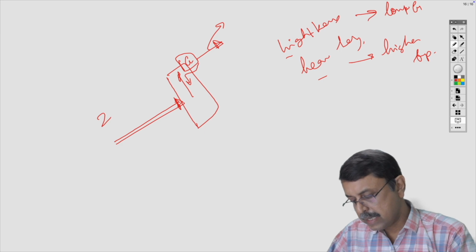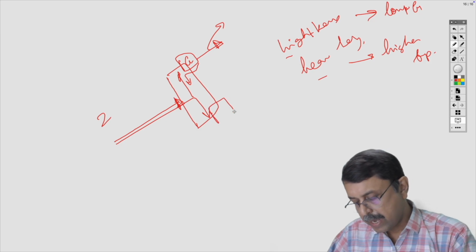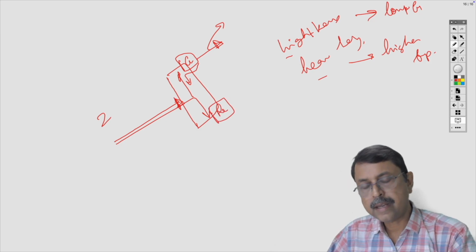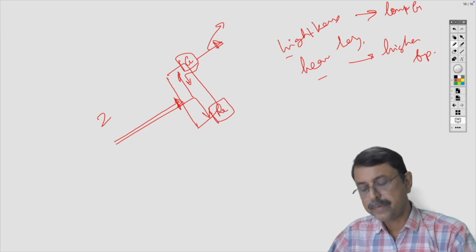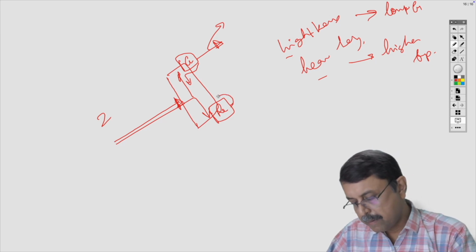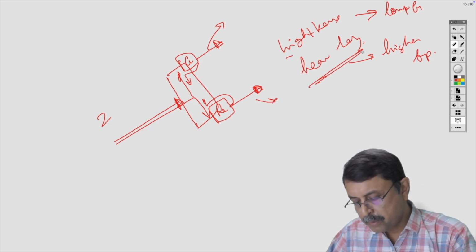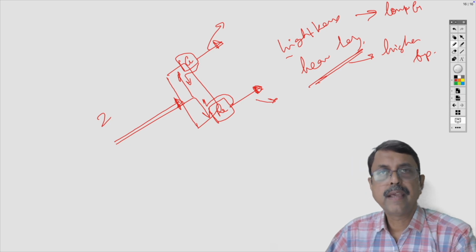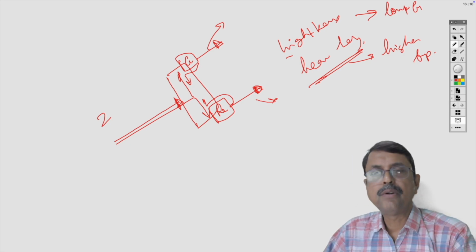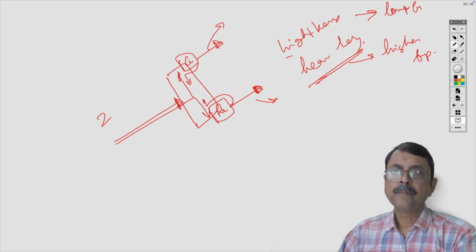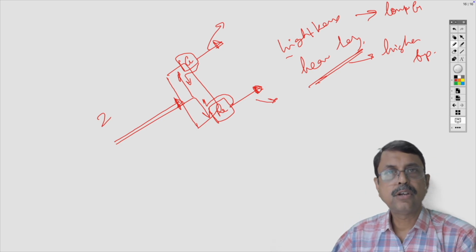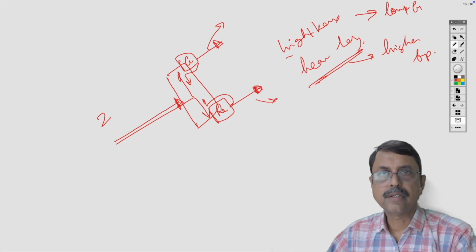On the other hand, the heavy key component tends to go down the column, and here we have a reboiler, which heats up the mixture. The majority of the mixture is sent back to the column and some portion is taken out, called the bottom product. This bottom product typically has a higher amount of heavy key component and very little light key component. That's how the light key and heavy key components are separated through a distillation column.